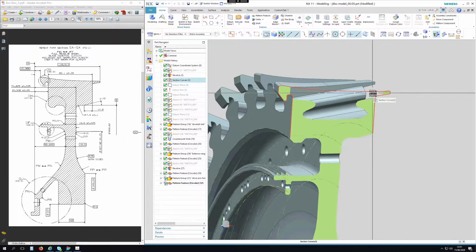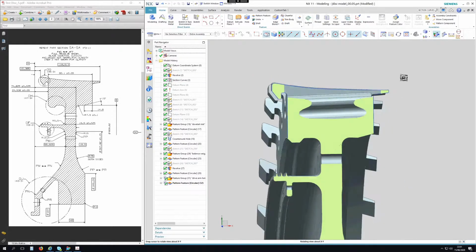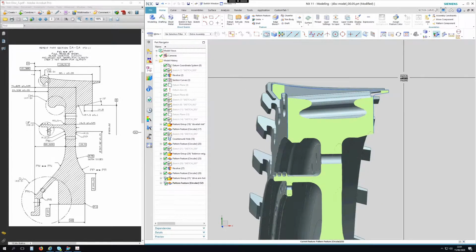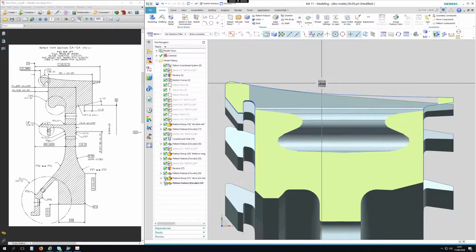You can see here now, I can see the section curves. Just press F8 to line that up. So you can see the difference between the background line, and the line where you'd need to machine it. So this would be where you need to machine it before you put the slots in. So when this gets turned, you turn it to this shape. So this is the shape we need to highlight and define.